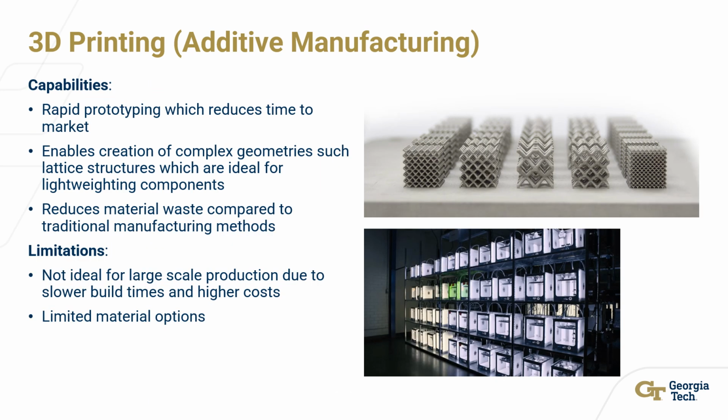3D printing has many capabilities, including rapid prototyping, which reduces the time to market. This is essential for engineers to be able to take their ideas and turn them into reality very quickly, which allows them to test and get real-world data and make design decisions faster than they ever have been able to before. It also enables the creation of complex geometries such as lattice structures, which are ideal for lightweighting components. This is especially useful in the aerospace industry.